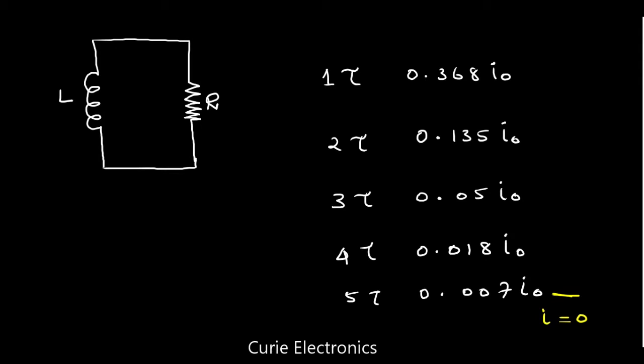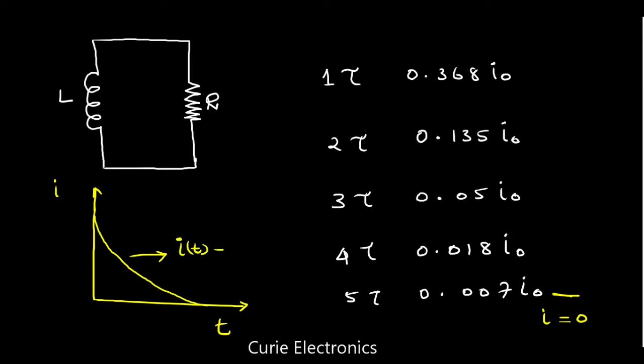Now what is one more thing we have to do? We know the equation for representing that curve. What curve? We got the decay of, this was I. We got a curve like this, an exponentially decaying curve. This was time. And this curve is drawn using the equation I of t, with respect to time, equals I naught, the maximum current, multiplied by e to the power minus t upon tau.